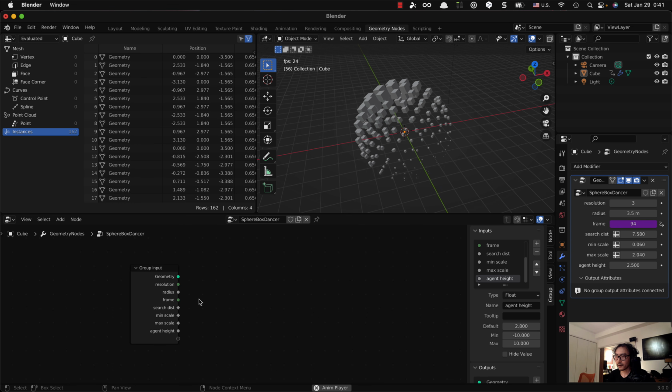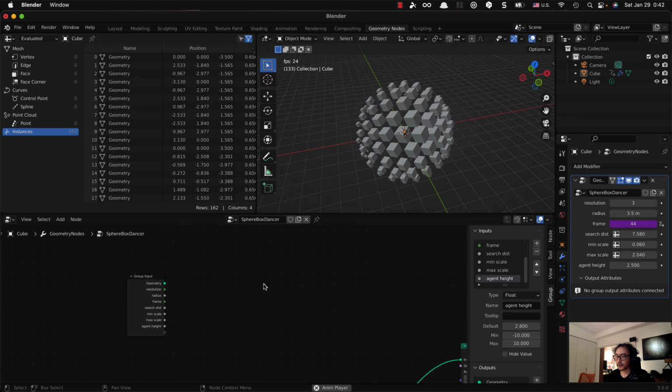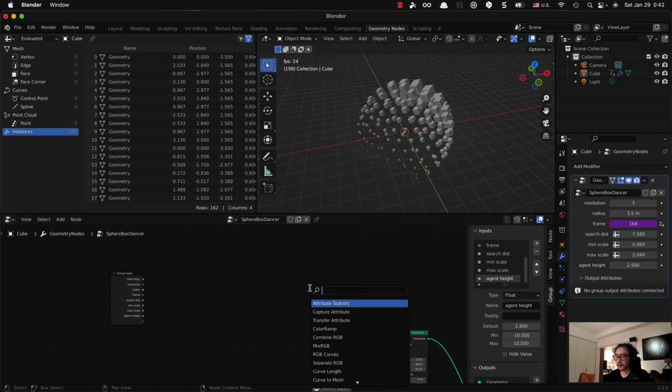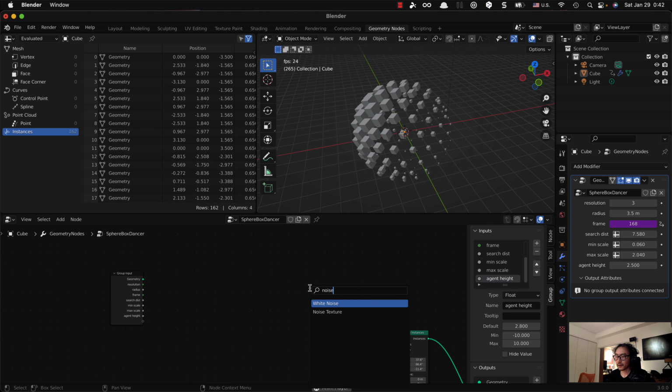If the input value is far, like if you input the value 0 and the value 10 at the same time, you get a really far value in between those two values as an output. But if you input 0 on one side and 1 on the other side, where the distance between those values is close, you get a really close random value like 0.1 and 0.2. Let's just try to see it in the actual node, how it works. So search for noise texture,